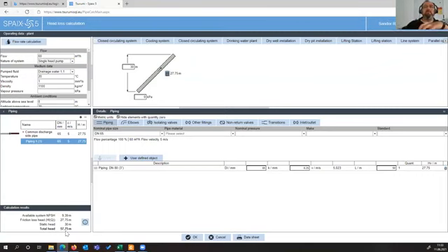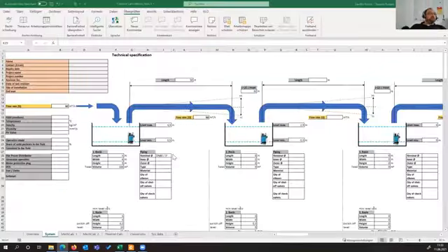So if you got information from your customer, we have a 3-inch piping considered in our calculations without knowing the inner diameter of the piping, and we select the pump as we always do, after installation that system will not work only due to the smaller inner diameter. This is once again for you all very important to have this info.